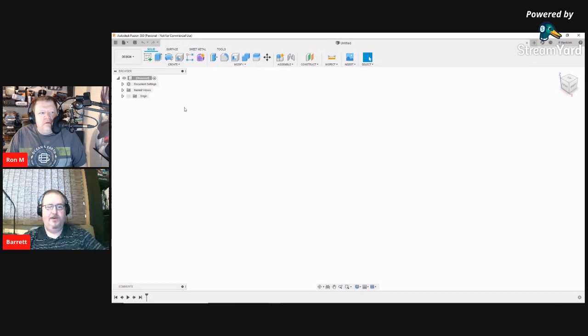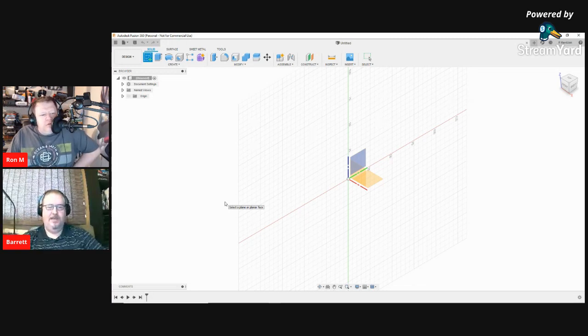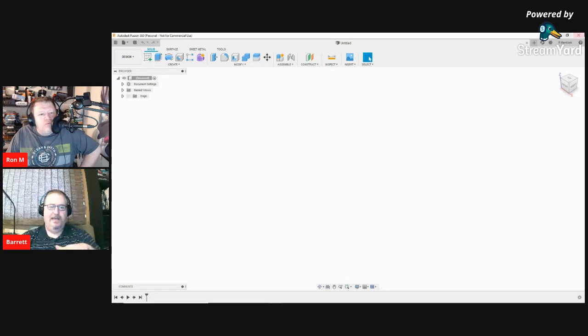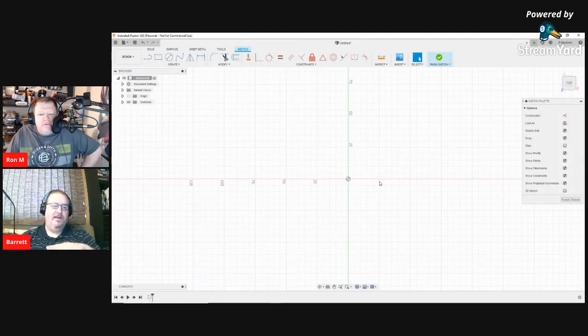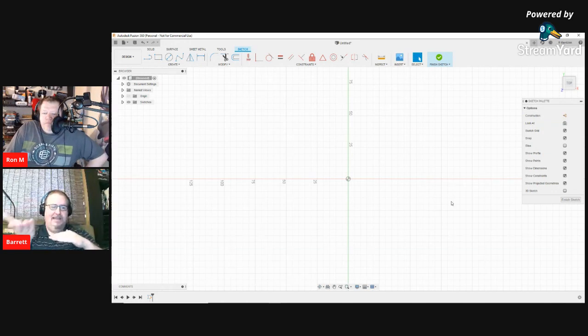So now if you go to the sketch, you'll notice that the planes are oriented a little bit differently. They're kind of turned around from where they were. So if you make your model now with the bottom plate being on that, can you highlight the bottom plane there? We have to recreate that. So yeah, this bottom plane right here would be essentially the bottom of your object. The bottom will be wherever it is, but that is a representation of the plane that would be parallel to the surface of the bed.